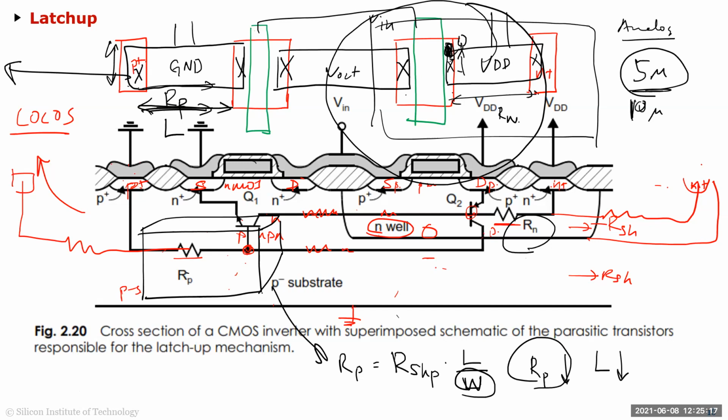So when you do a DRC, like you did a DRC yesterday, and you did LVS, typically this rule you'll never find in your DRC. So this is something as a designer, you have to make sure of. But for a lot of the newer technologies, they're trying to put some of these latch up rules into the DRC, because it's getting so complex, and it costs millions and millions of dollars for people to spin each time they make a mistake. It's a huge cost to companies.